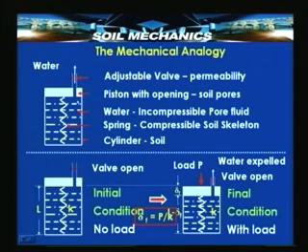It is this which controls the flow of water, and therefore, this is what is controlling the rate of transfer of load from water to the solid grains and contributing in turn to the compression of the skeleton.